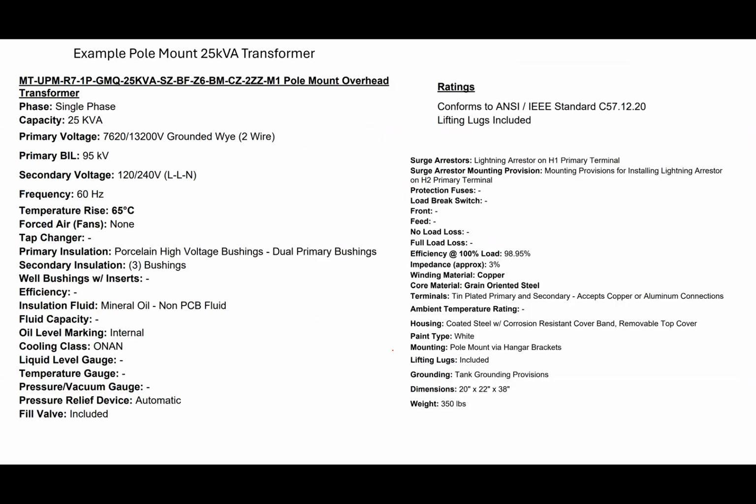Okay. All right. So in these systems, here I've got a pole mount 25 kVA transformer, and I took all of the data from that transformer to see what we typically see when we're looking at these ratings. I see the capacity, it tells me is 25 kVA. That's the total amount of power this thing should process. And they're not meant to deal with different levels of voltage, right? So it was rated for, it says here,